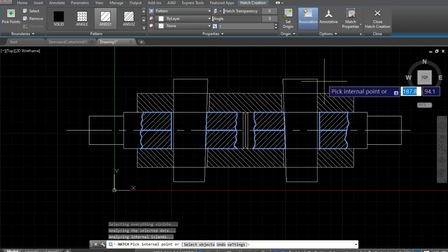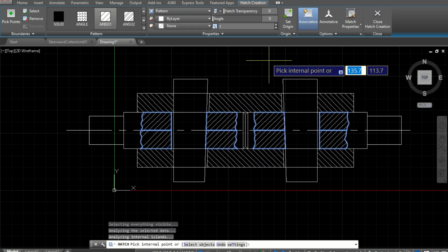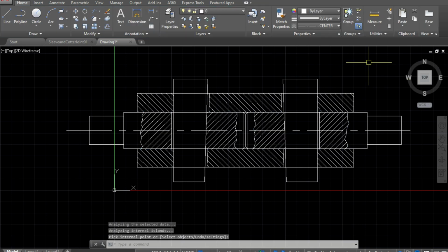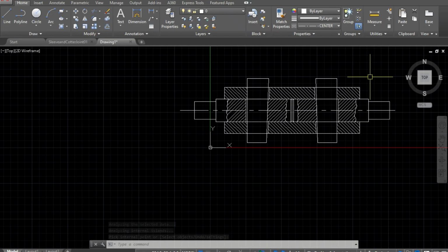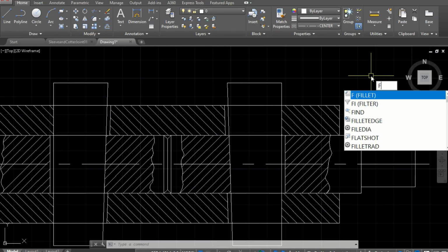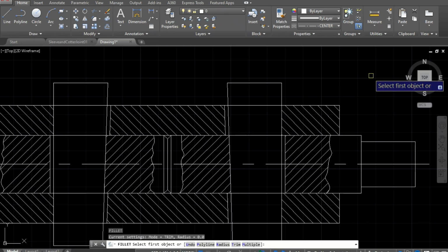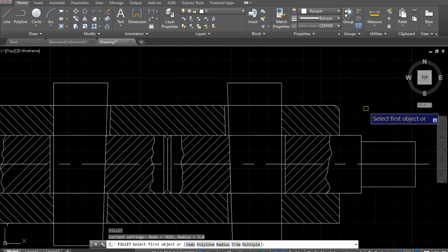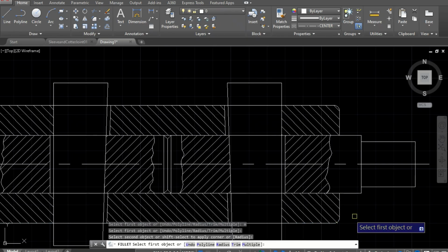Now we have done the sleeve 2D drafting using AutoCAD for creating the sectional front view of the sleeve and cutter joint. This is the sectional front view of the sleeve and cutter joint. And now let us give some fillets. Fillet, the radius is 3 mm in this region between these two edges, and let's give multiple, enter, so that we can give all 4 sides.